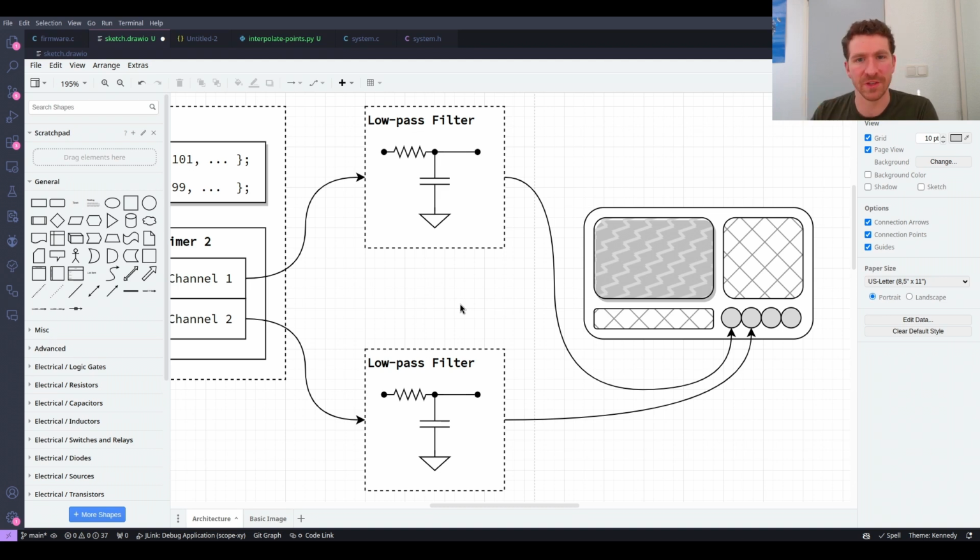And of course it matters which resistor and which capacitor we use, right? You can't just put any two together. They will always make a low pass filter, but we actually need to tune this to be filtering out specific high frequencies, and leaving intact specific low frequencies that we're interested in.